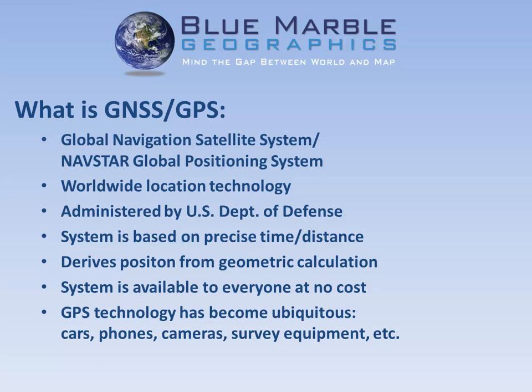Is there anything other than the price and quality of the GPS receiver that affects accuracy? Well, most of the receivers you buy today, and certainly the technology has, as is typical, improved in quality, and the prices have come down. Many of the receivers have been designed to allow differential GPS or an onboard correctional system that will typically get your accuracy down to within about 3 or 4 meters. So, for many applications that is fine. Obviously, for survey-grade applications, that's not going to be enough.